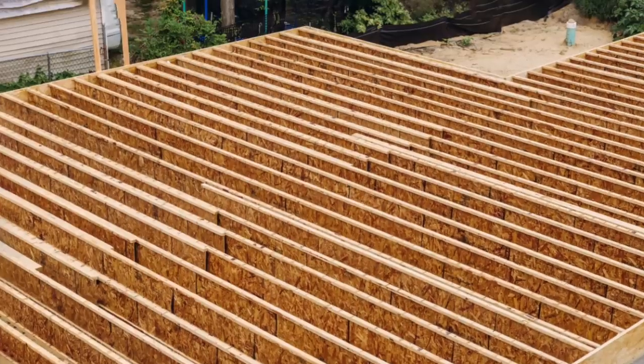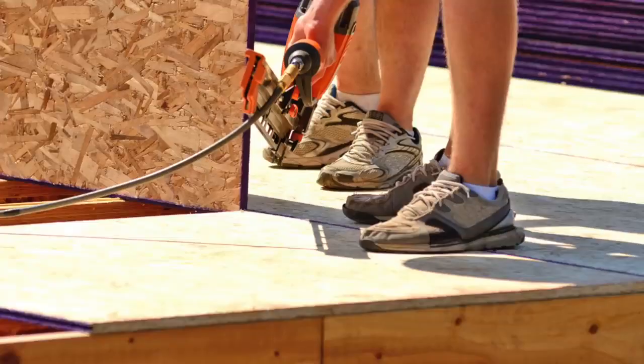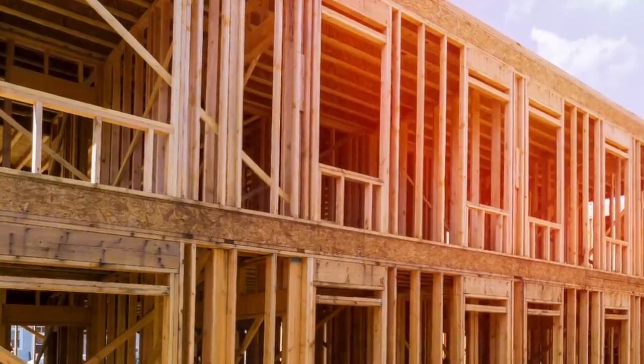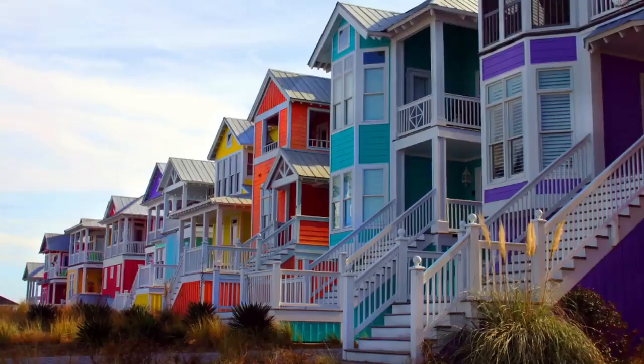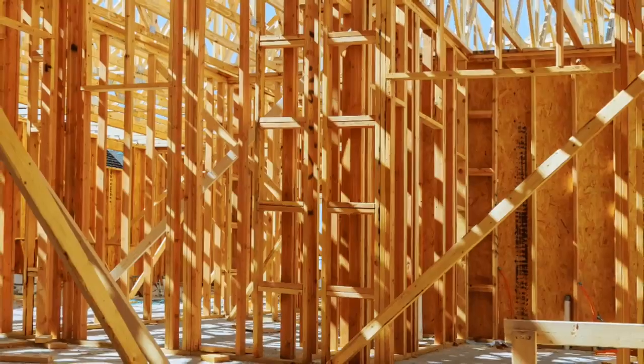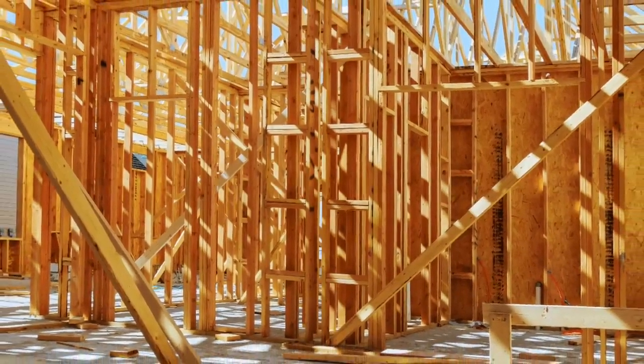Okay, continuing upward. Higher floors in a house are built much like the first floor. Joists sit on the top plate of the wall below. Subfloor covers those joists, and the next frame wall sits directly on that subfloor. It's pretty much exactly the same floor to floor. Taller houses may require more beefed up framing, especially on the bottom floor. But terminology-wise, words are going to have the same meaning everywhere.